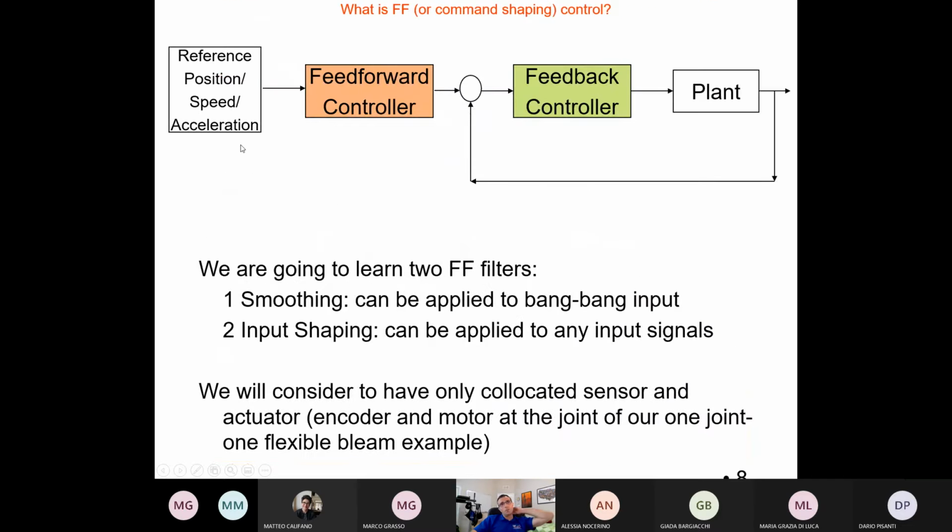And so for feed forward, really we're not doing any feedback control. Basically what you're going to do is this. You have a reference motion for the hub. So you want that to be reoriented, I don't know, 45 degrees, and you would like to do it maybe time optimally. So if everything was rigid, you would do it in a bang-bang, but you can't.